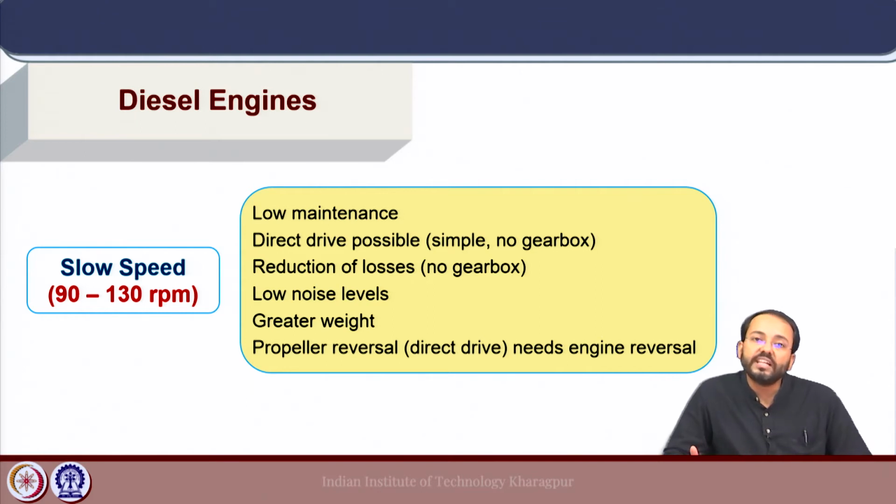Here we can have considerably low noise levels, because this is a slow rotating engine, but the weight will be quite high for these kinds of diesel engines. And the propeller reversal, because it is direct drive, will require the engine to also be reversed during astern operations.